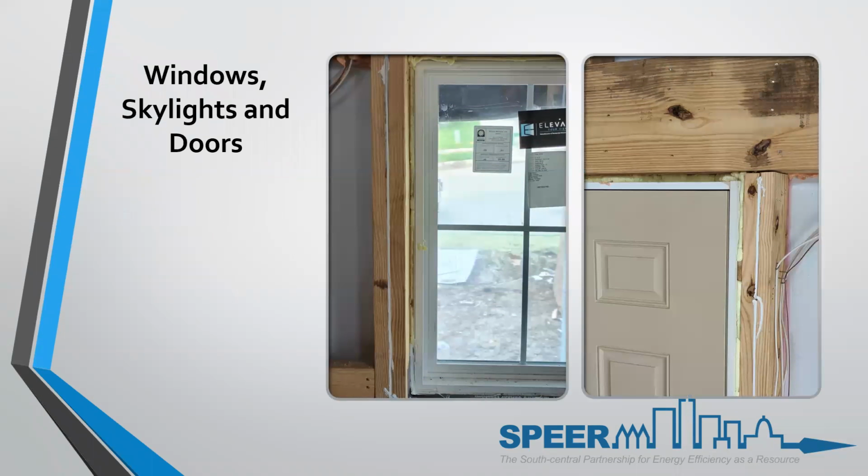The framing around the window is what we refer to as the rough opening. The rough opening is always larger than the window or door, and this allows for adjustment during installation. It also can allow for expansion and contraction in between. These small gaps must be air sealed with either caulking or expandable foam. This will prevent or lessen air movement around windows and doors.